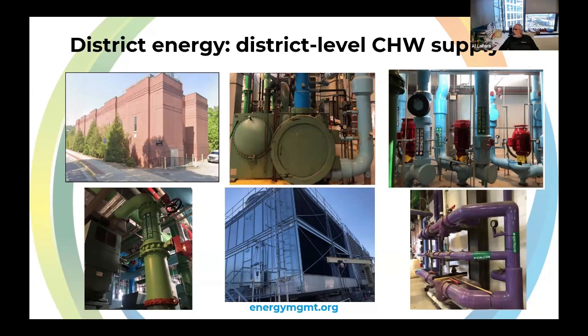One of the things we found is how critical cooling towers are. If your cooling tower goes down, then your wonderful brand new shiny chiller is offline. And when that happens in summer, that's a terrible situation to be in. So you need to make sure all your I's are dotted and T's are crossed. Are you outsourcing that PM to a contractor?